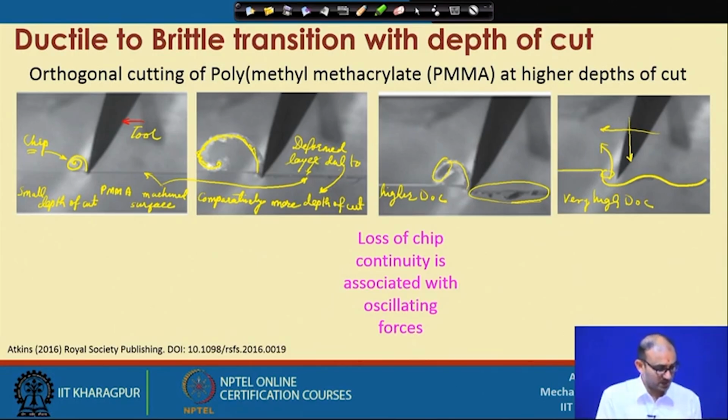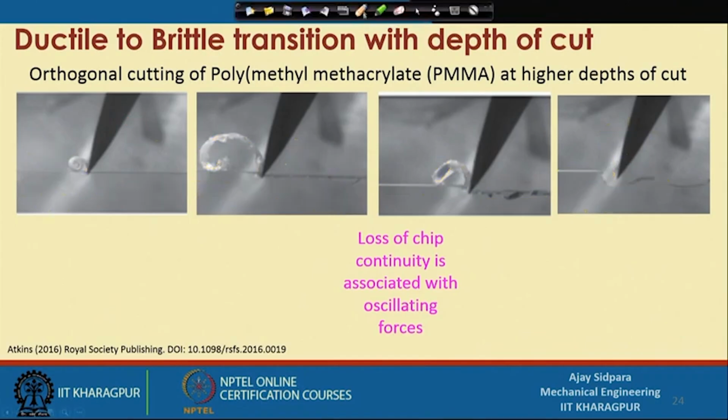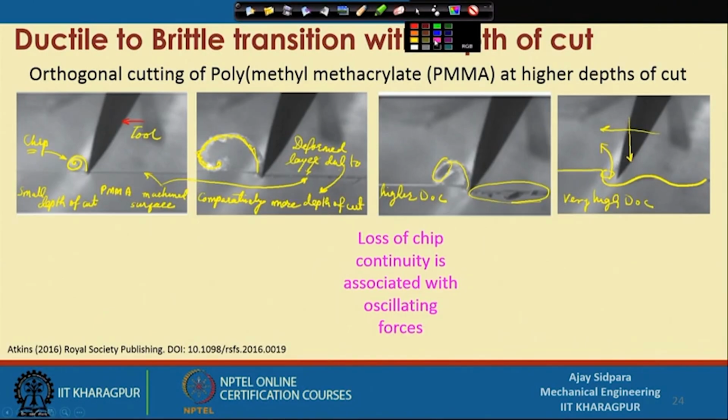So that we can understand what is happening in the machining zone. One way of doing this is to find out the force acting on the material. So, you put a dynamometer onto the workpiece. Let us put one dynamometer, a force transducer, on the top of the workpiece, and then cut with the cutting tool.